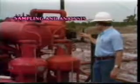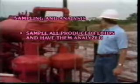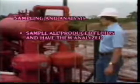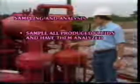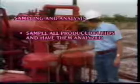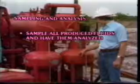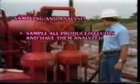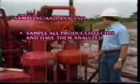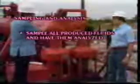All fluids produced at the wellhead should be accurately metered, sampled, and analyzed in order that an accurate recombination is obtained. Now off of these pots we can take samples to determine what our chlorides are off of the water pot, and off of the condensate pot we can get a sample similar as we did with the gas line and just put it in a jug of some sort, and then we can send that off for some sort of analysis. Samples are taken according to industry practice, and all sampling points and conditions of sampling should be noted on a line diagram of the wellhead facilities.